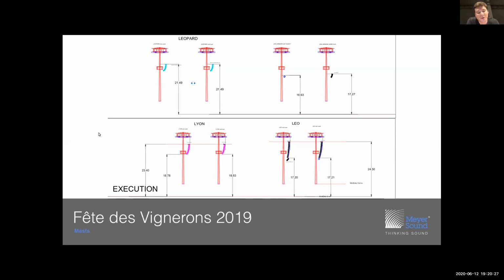This is also where we realized that not everybody was using the same coordinate system. I was taking the base of the mast as my zero point. Jean-François was taking the field of play, and most of the artistic direction was taking level 5.5 as level 0. Jean-François discovered that all the plans were right, the right scale, but they all had a point of origin in a different place. My original design, for example, was 2 meters higher.